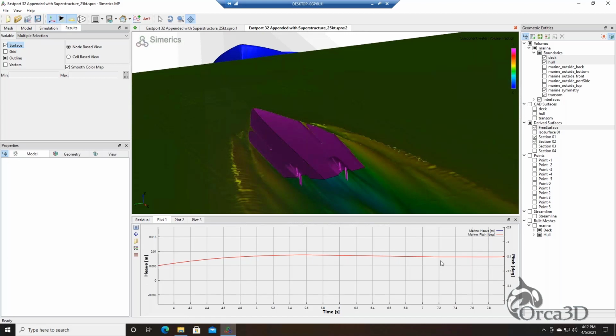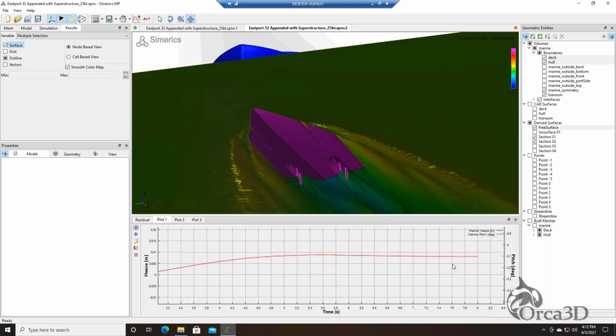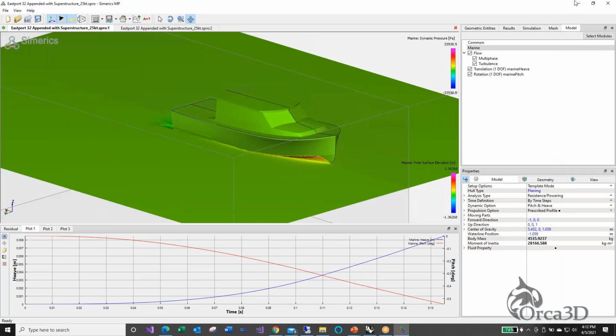So if this model was sitting with 0 trim in Rhino, but when you floated it, it had 1 degree, say plus 1 degree of trim, meaning the bow was down 1 degree, and now it's saying a bow up trim of 3.1 degrees, you would have to add the two in order to figure out the net change in trim. So this is dynamic trim, is what we call pitch. So that's an overview of how the process runs.